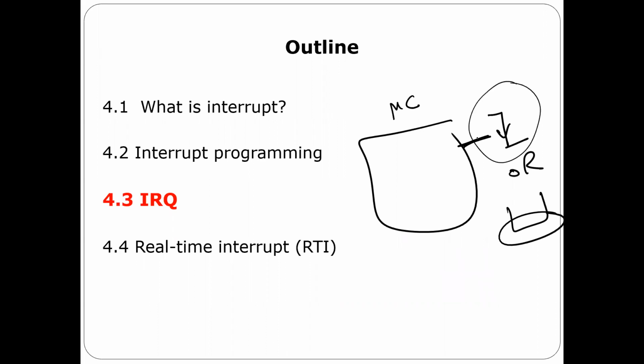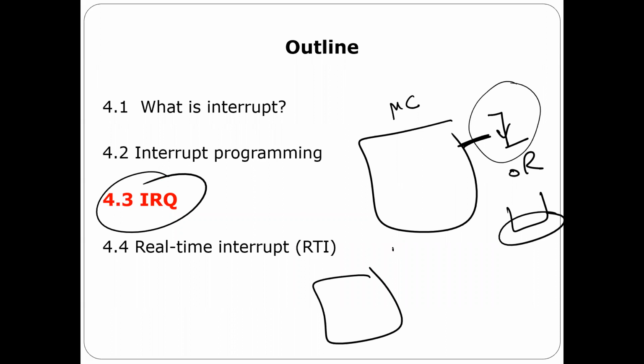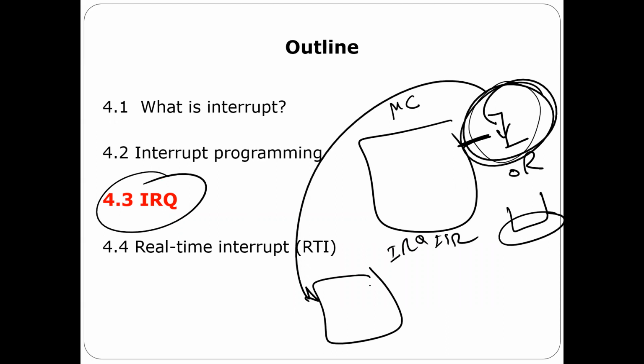Every time there is a falling edge here, you trigger what we call an IRQ interrupt. There is a subroutine for IRQ interrupts. Every time a falling edge comes, I'm going to call this subroutine, and then you can write here whatever you want to do when the falling edge comes. This depends on your application.